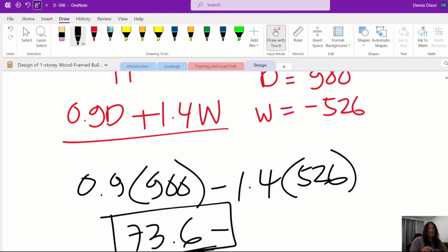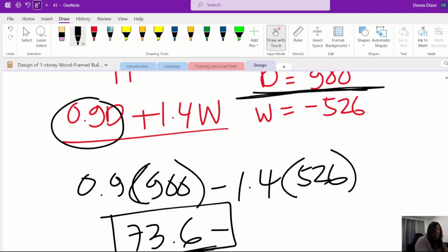But you have to be careful when you calculate for this one, because this dead load, this reaction, is just a rough dead load calculation. When we design the member for gravity, we assume the worst case possible assembly, assuming all the insulation is uniform at the thickest insulation at the very end.